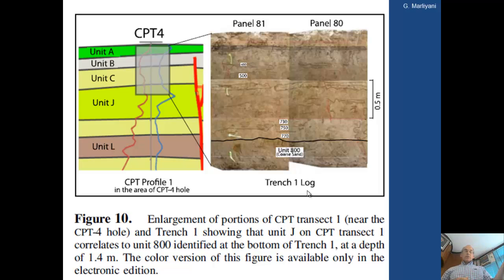Here was the nice thing. Gayatri could show with the trench log, this is 50 centimeters, a little bit of the change in her friction ratio profile, and some sense of the relationship between the interpretation of the friction profile from CPT and the very detailed logging. She sees, coming from up at the top here, this sharp transition in friction, steady, a little dip here in the middle, another one here. The point is that even though you're measuring friction every centimeter or less, you may only interpret layering that's more than about 10 centimeters thick. So we don't get the very fine structure, but we get the gross structure. But we can go deep.